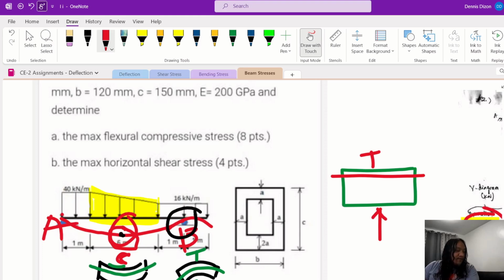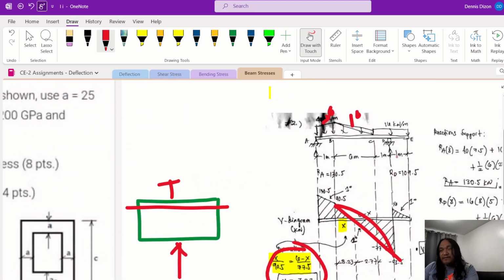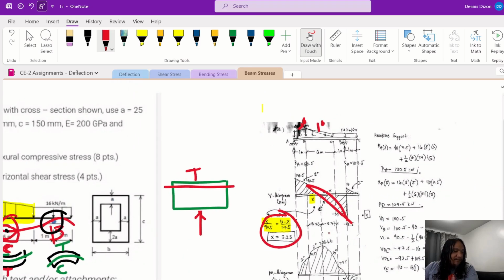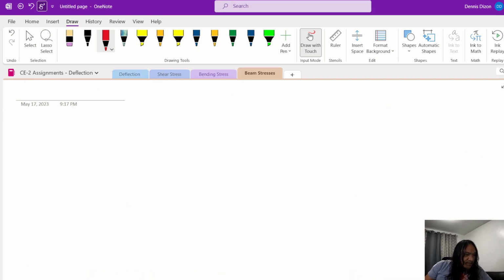So we will solve this again. He tried to calculate the reaction and then draw the shear and moment diagram, but he forgot that the load is already in the first degree, therefore the shear diagram is in the second degree, and you cannot use a direct ratio and proportion, like a linear ratio and proportion. So we will do this one again. So the load is, let's have another page, and then let's just insert the